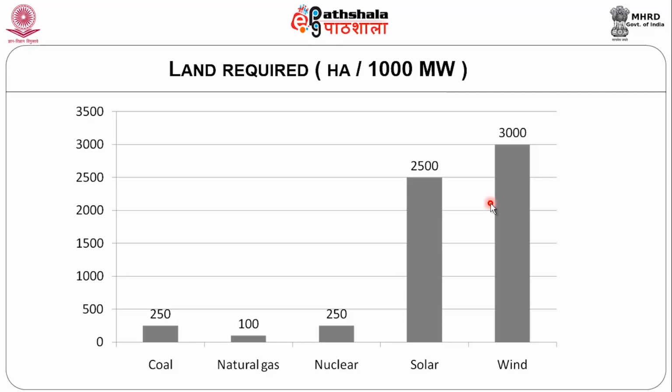So the maximum capacity factor we can go up to is 59.3%, but because of practical reasons, the best turbine could perform with 40% capacity factor. Generally, a wind farm's capacity factor would be around 0.25 to 0.3, that is 25% to 30%, but the best wind farm performs at about 40%.